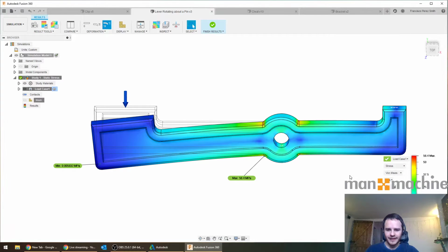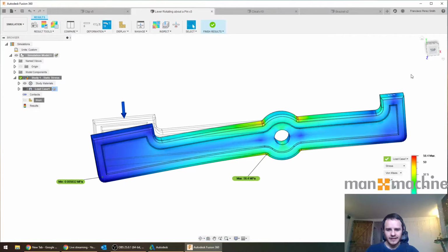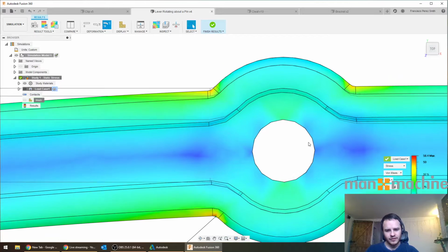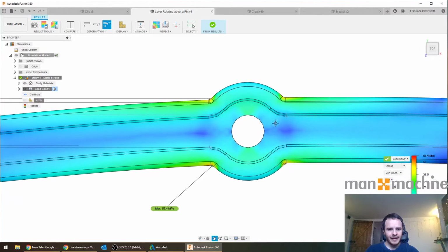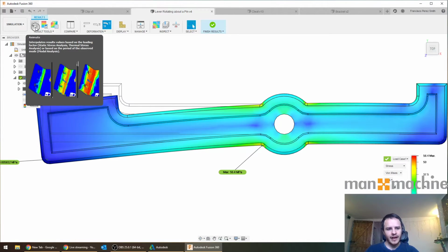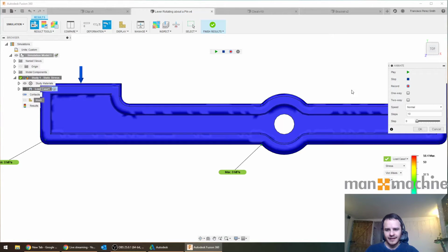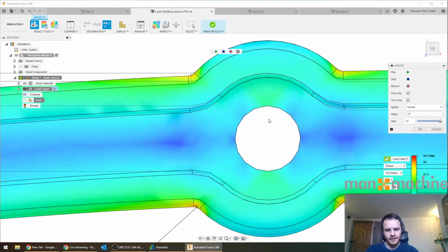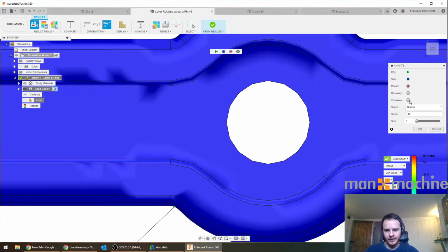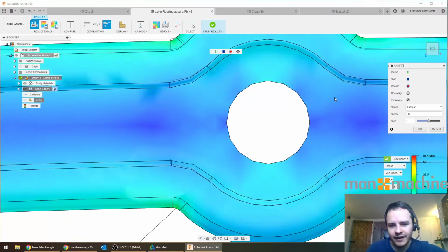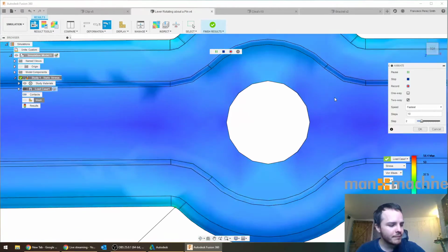Okay, so let's have a look at what we're looking at. What we've got is our lever. Now, we might want to say, oh, is it actually rotating about that pin? It kind of looks fixed. We can actually inspect it by animating the deformation. So what we'll do is come here to animate. And here, when we click play, I might set it to go 2A and increase the speed. There we can see the lever rotating back and forth over the pin.